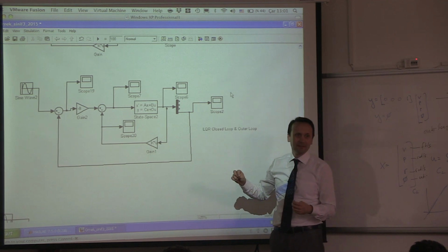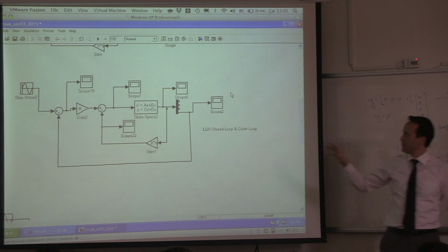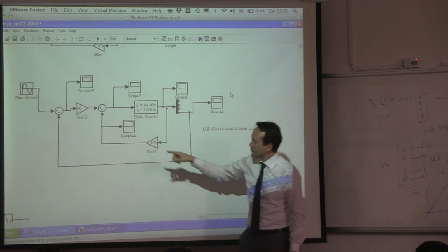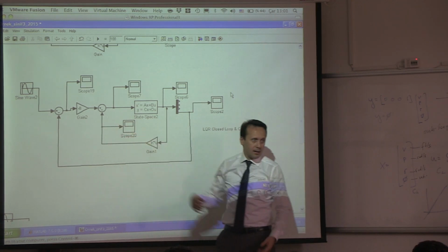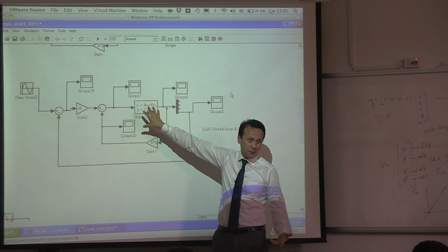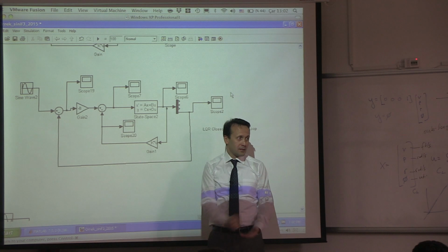You understand that? We do that in the lab all the time. Put a little airplane figure that flies and connect your joystick over there and then start flying. And then you can put your model over here. You need a model. It can be linear or nonlinear. Put a linear model, design the controller and see how it flies.